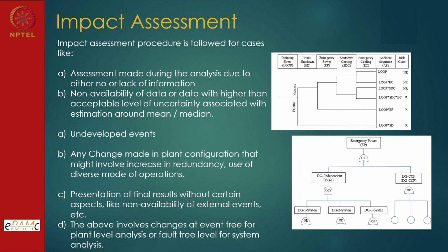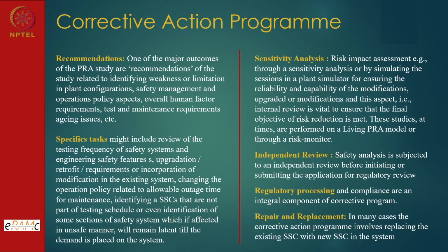I'll go and survey and see what is the range of seismic impact from other studies, and I'll use that range, maximum and minimum, and I'll demonstrate where my plant's risk is. Otherwise, performing a seismic risk assessment might become prohibitive because data is not available, or even if it is available, it is very low. So these are management techniques, but it should be made clear what the impacts of these data or situations are on the final result of the problem.